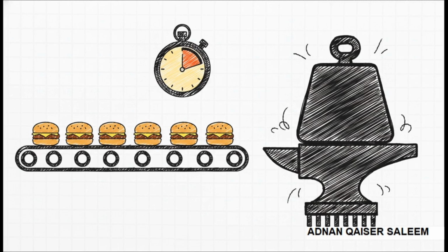But to keep this fast-paced assembly line humming without constantly waiting for slower main memory, RISC architectures require a ton of internal registers for extremely fast data access. Oh, and this is crucial. Only specific load and store instructions are allowed to actually access memory directly.